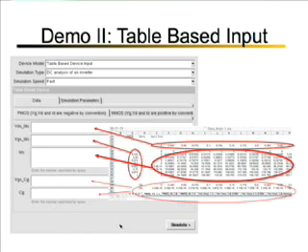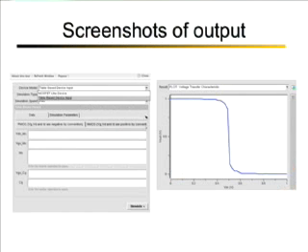And then once you hit simulate, it will simulate with these IV characteristics. This is just to show one of the screenshots of the output, and it shows how the VTC of a typical simulation run looks like. And if I scroll down from the results section, you can look at the parameters like VOL, VOH, and gain for this particular DC characteristics.